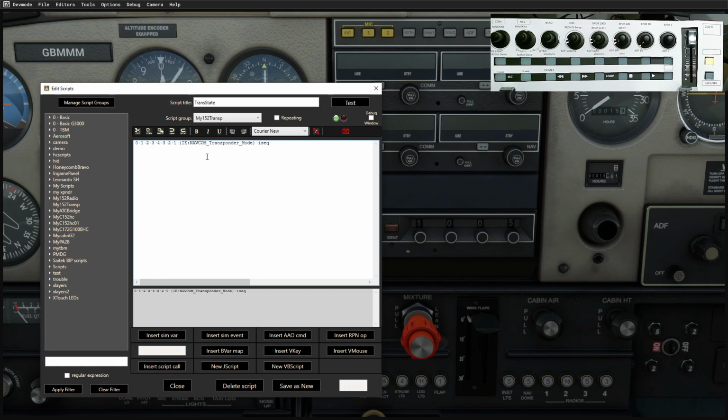The difficulty with it is if you had it as an ordinary sequence event, it would step through looking at this variable here, and it would find the first instance of a match. So if it was in mode 3, it would find this 3 here and go to the next one, and that will be the mode that it will put it into. It would never get to this mode here and go 3, 2, 1, because it would instantly find that 3. So what we want to do is to keep an index. That's what's called an index sequence, and it will remember where it was last and only start the matching from there. It won't start the matching from the beginning each time.